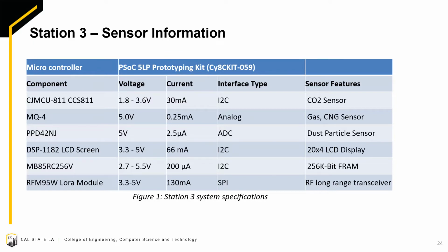This information needs to be displayed locally as well as stored in a cache in case of a communications issue. That would be our FRAM module, the lovely MB85RC256V. With our components finalized, we end up with a microcontroller, 3 sensors, a display, a communication device, RAM storage, and a 9-volt adapter for power.